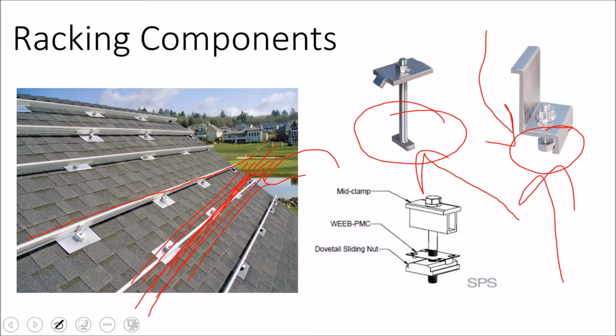And then, these stainless steel bolts, they're not designed for multiple use. And so if you take them apart when you're installing, and you get the first 3 or 4 modules on, and you realize that you didn't square the racking, and so the modules are trying to creep up at an angle because your rails are oblong and you're trying to bolt a rigid rectangle to an oblong surface underneath, and it causes the modules to torque and skew.